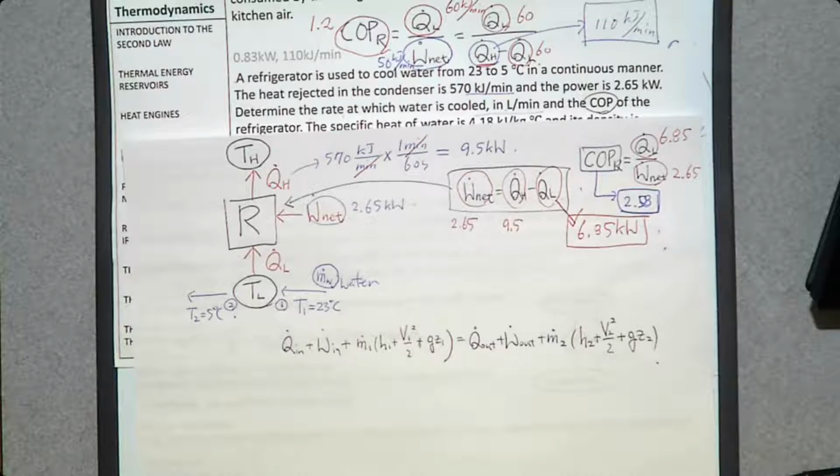Then, are we going to use this energy balance equation as is? No, we are not scientists. I'm not offending any scientist, but I'm just saying that we can simplify this equation. How can we simplify this equation? We can neglect kinetic energy change between these two. Can we? Yes, there's only one inlet, one exit, unless there's a significant diameter change between the pipes at the inlet or exit.